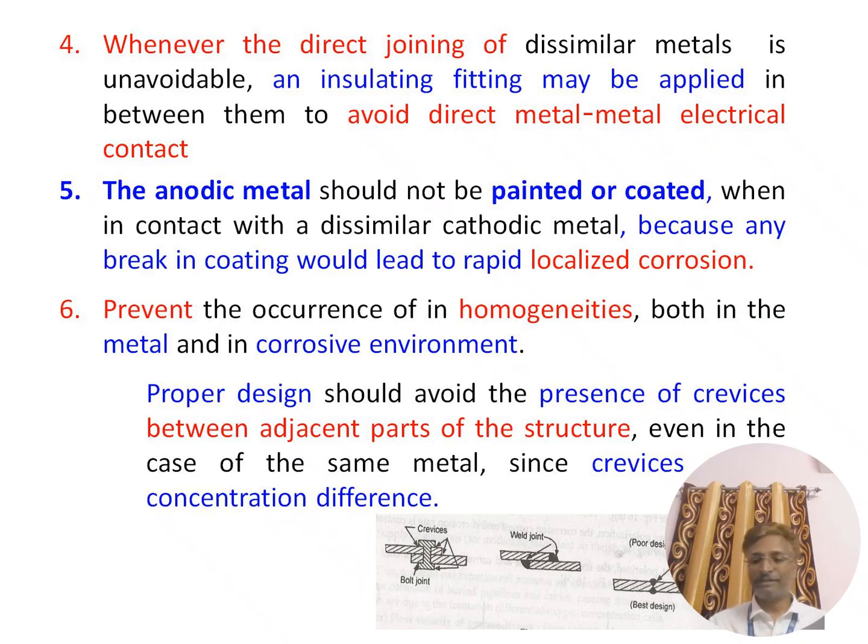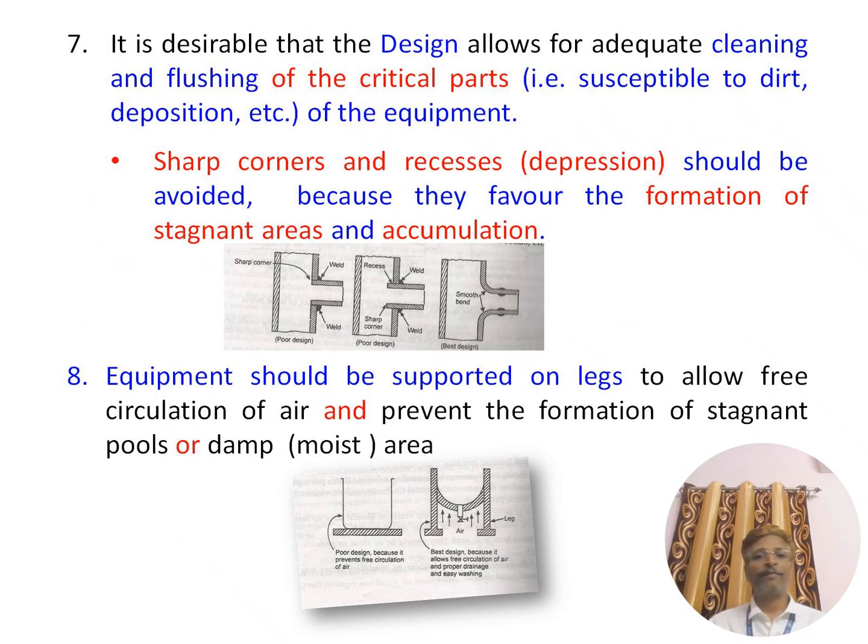If you look at the picture, sharp corners should be avoided, and the joint and bend. Even in many of the objects in your house or in your office, if you look carefully where corrosion occurs, it is only at the joint, the bolt and the sharp object. Those kinds of parts are where the rate of corrosion will normally occur. That is very important.